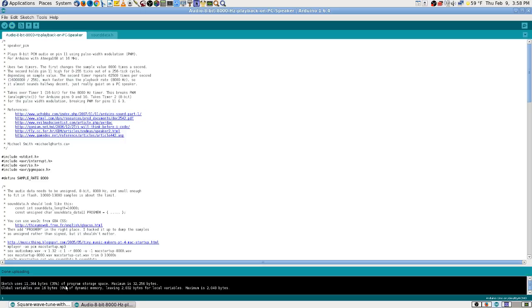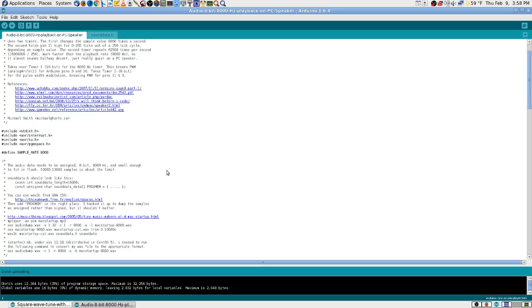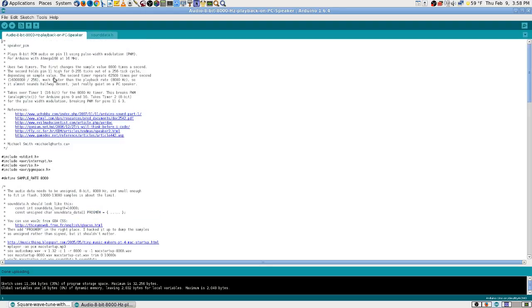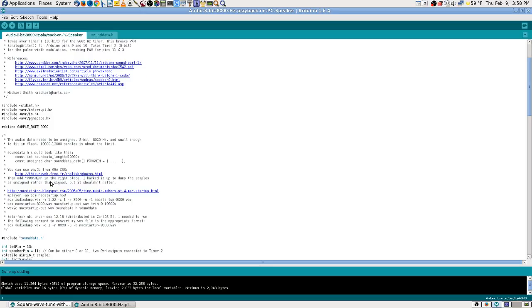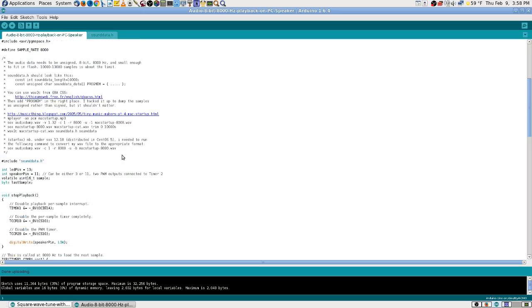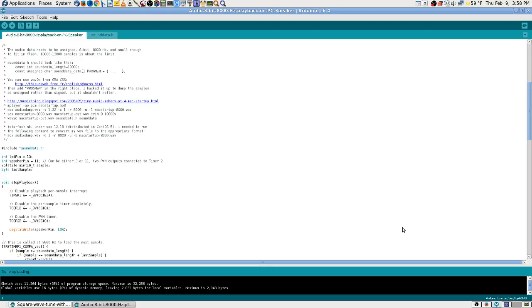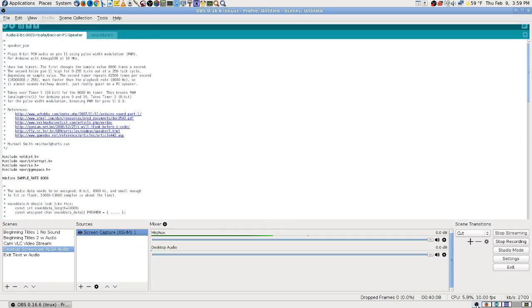Done uploading. Oh, I think we have to be on a different pin. I don't hear anything. I think it's going to be pin 11 or something. But it does say done uploading, no errors. So that's a good sign. Just got speaker pin 11. So I'm going to unplug the Arduino to change that because I do not want to risk messing it up.